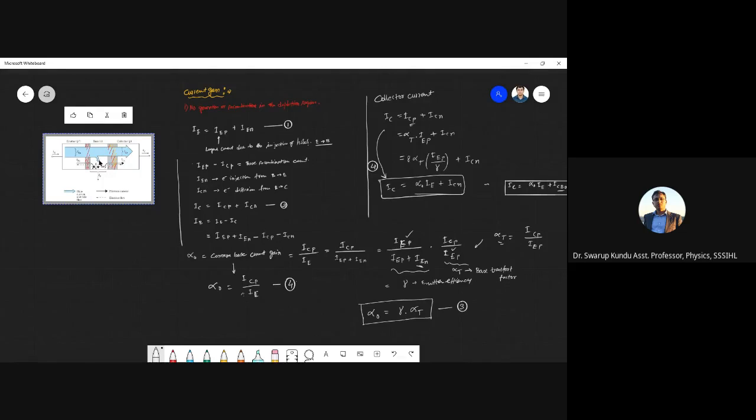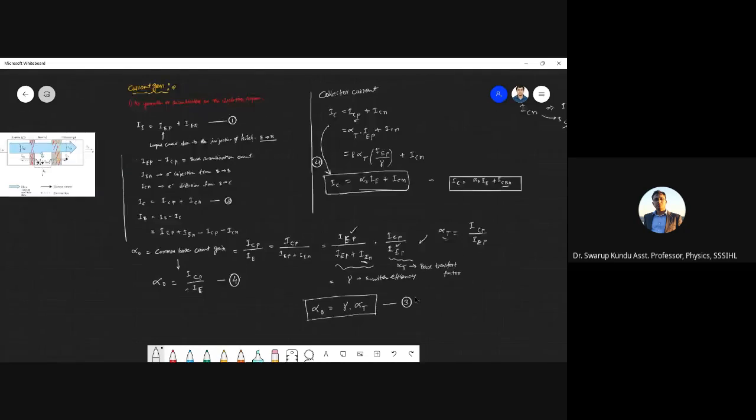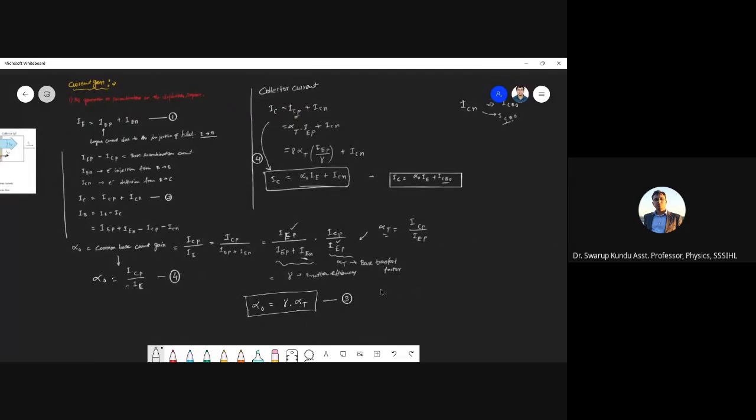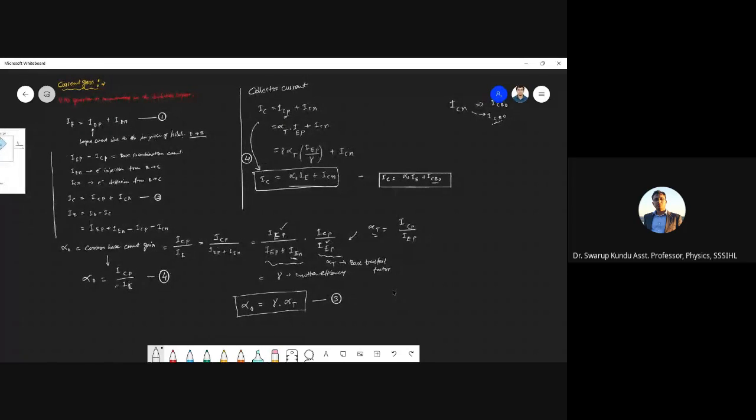And the thickness is determined by the diffusion length of the hole, or the electron if it is an NPN transistor. And it has to be less than the diffusion length of the carrier. Otherwise they will recombine, right? So to reduce the recombination loss, we minimize the base dimension. Okay.